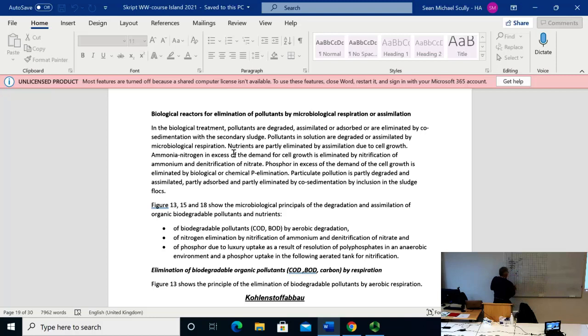And there we have 1 liter, and it is about 40 grams of COD per day, 1 liter per day. It's 1 gram of nitrogen per day, and it's 0.2 grams of phosphate per day. So in our biological reactor, now we get our nice microorganisms here.